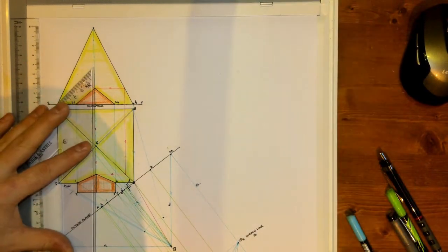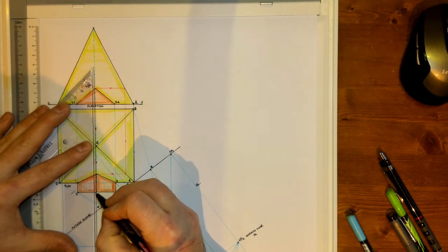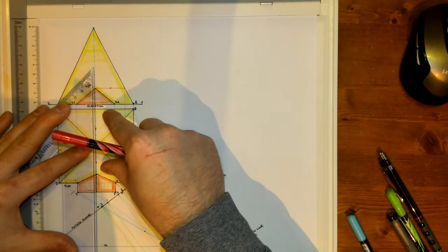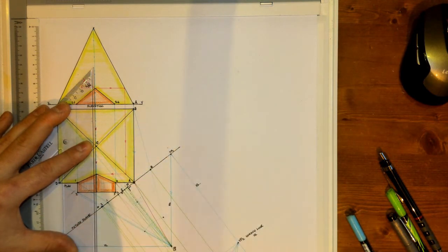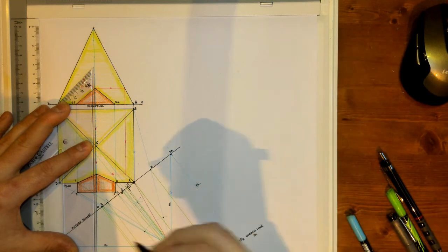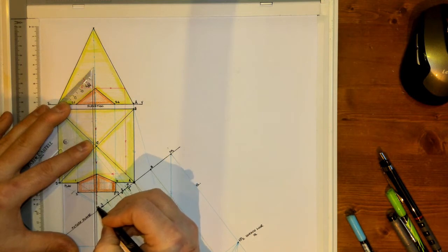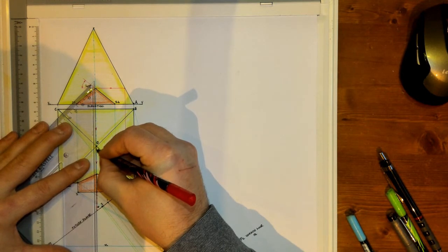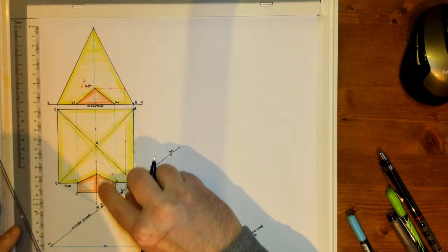Now, I could do O a different way than what I'm going to show you now, but I want to show you this one because I think it's more transferable. What we're going to do is transfer that point O on to the picture plane. So, line up point O in plan, and we're going to slide it. Imagine if we were taking this whole view and sliding it down to the picture plane till point O was intersecting that picture plane line. That's essentially what I want you to visualize in your head. So imagine sliding point O, and I'll use a dotted broken line in red so you can see. Extend that line all the way, so you can see it. So take point O, slide it on.